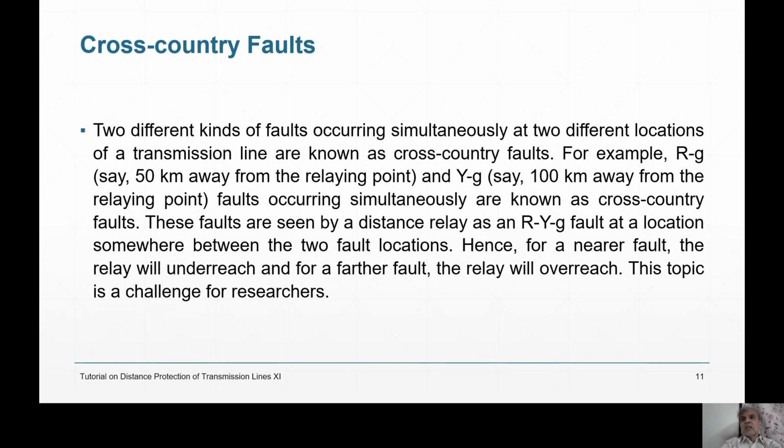So if you consider that, and if the fault is after the capacitor, means after the bus, then if that energy difference can be calculated, you can apply a correction factor and measure the correct impedance.